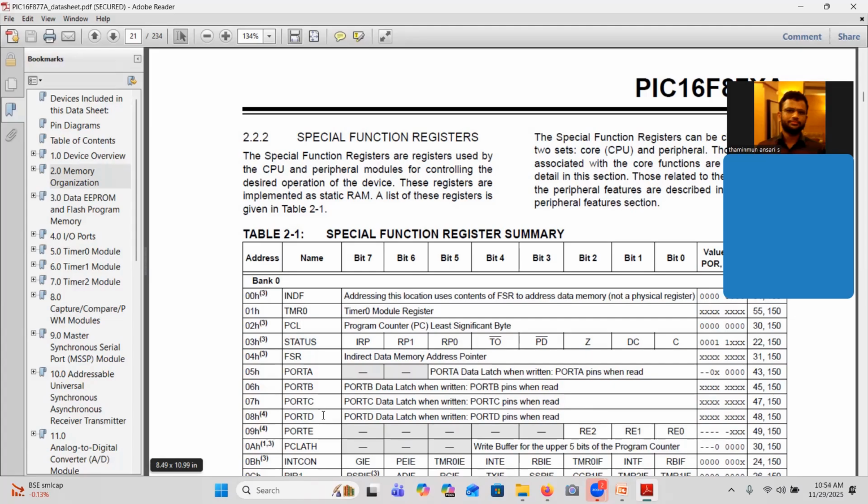That is part of the microprocessor. Here, yes, it is part of the microcontroller, as well as additional registers. So it appears strange to you why we see the program counter in the location of the peripheral registers. It is because in a microprocessor there won't be timer or port registers. Only registers related to the microprocessor will be available. That's why you feel it is strange.